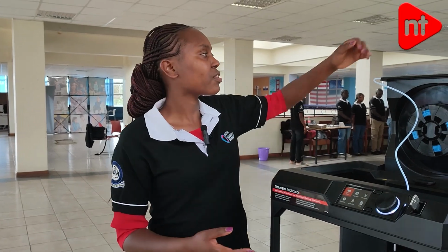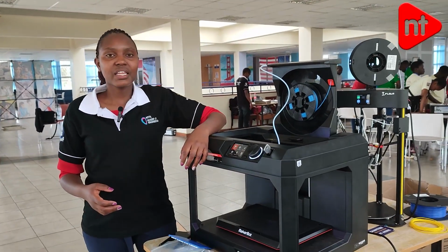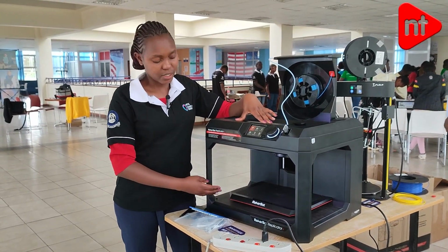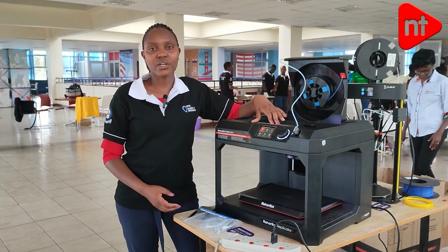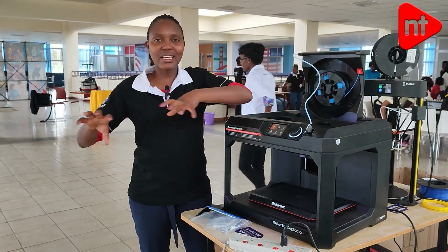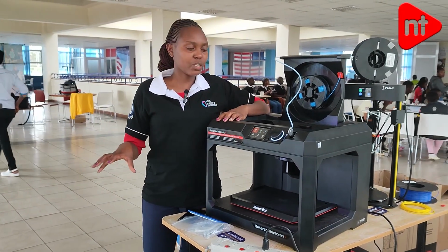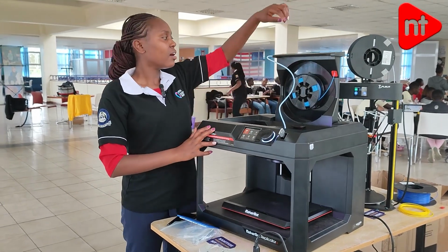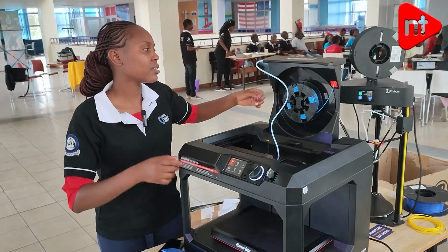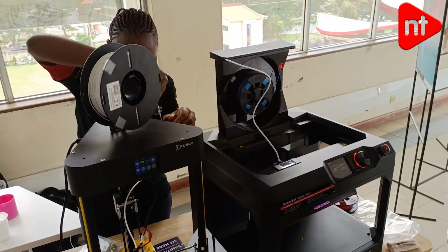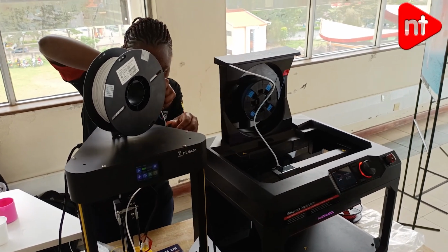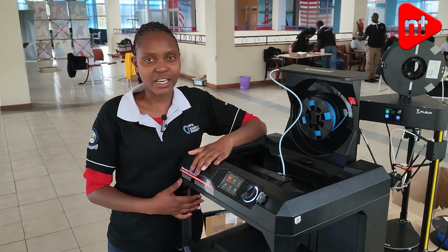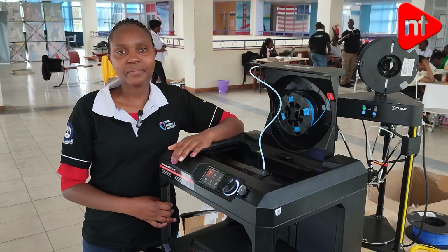Some of the software I've used for this kind of printer are the Cura software and Ultimaker software. For this one, just like the name of the printer, we require software called MakerBot Print, which you use to prepare. So the design is basically done using a normal computer, a laptop, and then you can transfer your work using a removable storage like a USB flash disk or even an SD card, the micro disk, which I use for this kind of computer. So once you prepare your work, you slice it for printing, then you bring it to the printer, you set it up for printing, and the printer takes up everything. And that's how basically you do the 3D printing and designing.